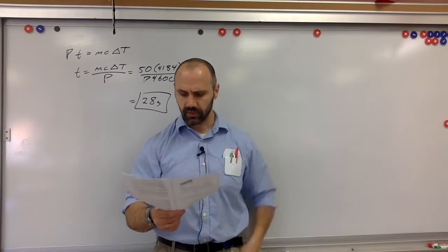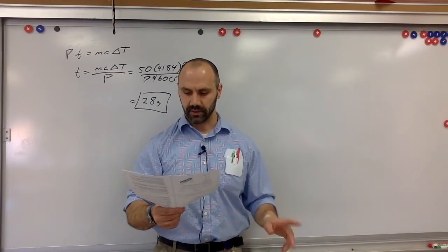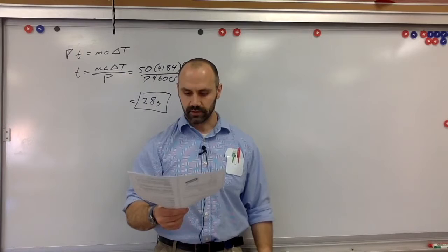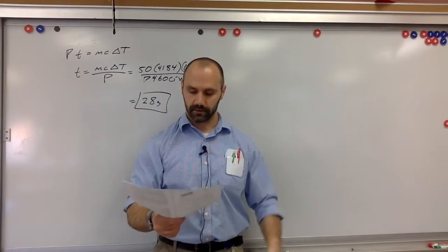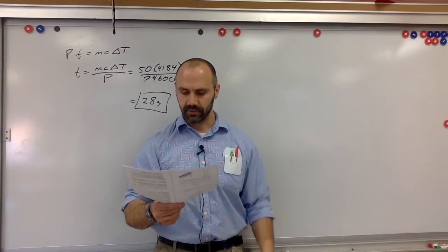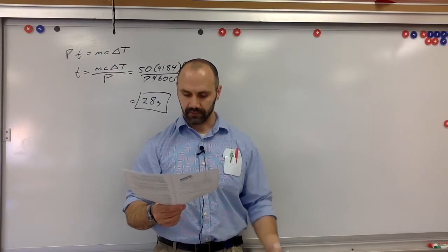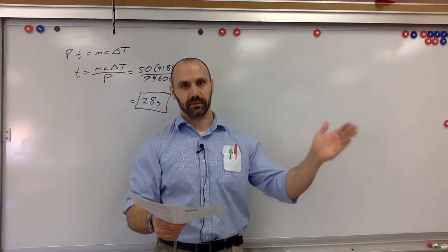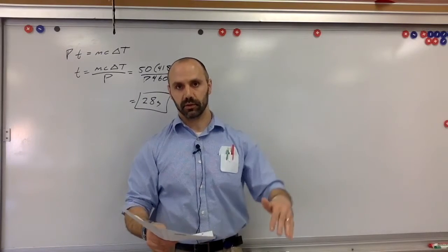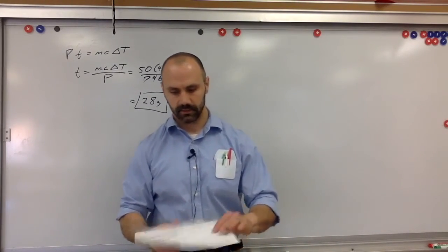And then what if the semiconductor's temperature coefficient of resistivity alpha is larger in magnitude than for conductors? That means you get a greater change for the same amount of change in temperature. And what does it mean if semiconductors' temperature coefficient alpha is negative? That means that the higher the temperature, the smaller the resistivity of that material. Okay, and that's it.